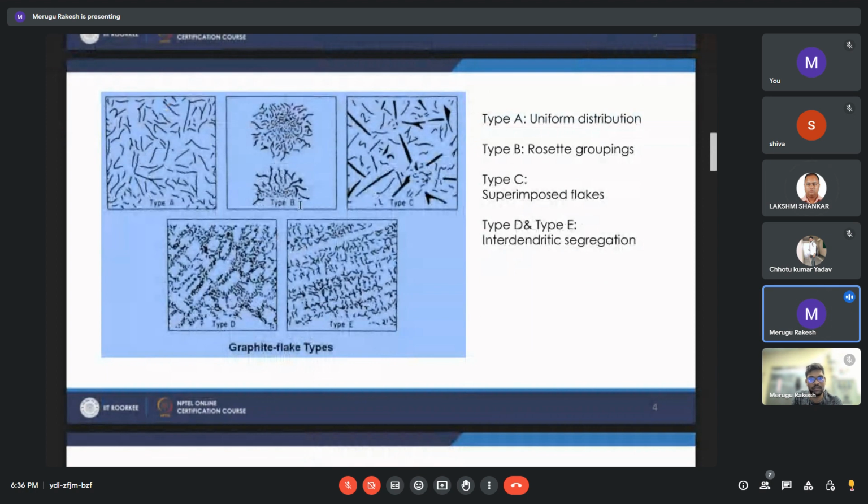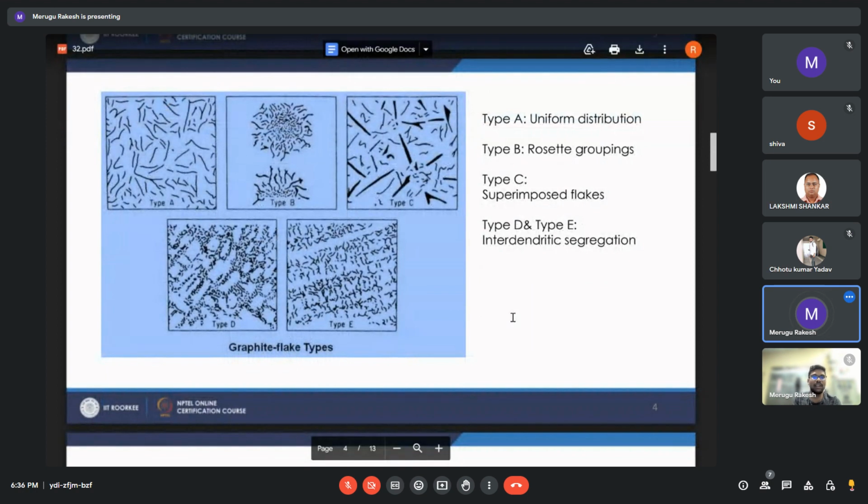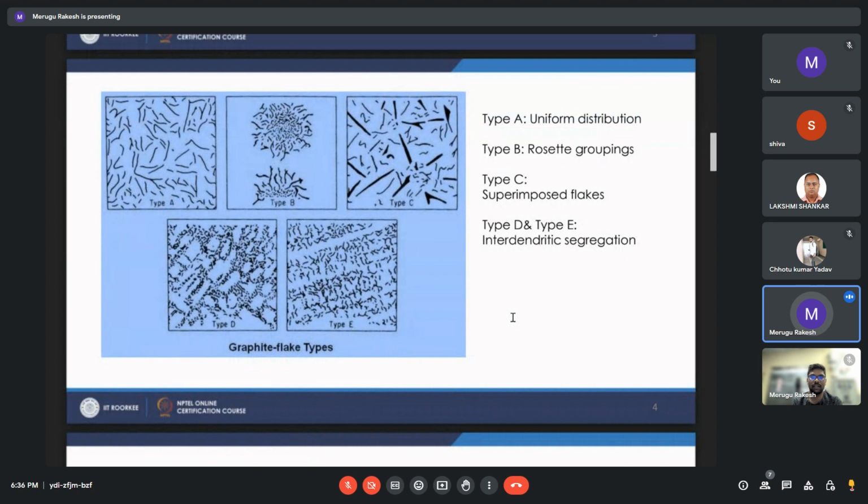So we have to go by this metallurgical process, take samples from the cast product. Once we observe them under the microscope, we get the percentage of graphitization that is formed with different process parameters, for example pouring temperature and holding temperature in the heat treatment process. You repeat the experiments a number of times, get the statistics, and finally you can get to know the parameters: at this parameter, I can get this much graphitization.